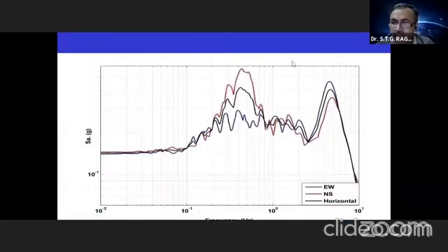And now you can see these types of special spikes are the long period. Generally, the response spectra will show one peak and goes here. But when you are in the near field, you will see some special other spikes around 4 hertz, 3 hertz also. You will see this in the time histories.